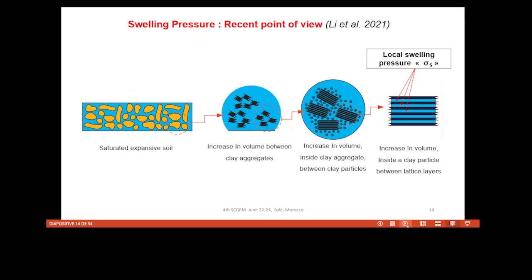A new point of view about the swelling pressure, because when we come back to the structure of saturated expansive soil, here we have the particles and water in case of full saturation. But if we go through the details of particles, we know that the particles are composed of clay aggregates, and we have some chemical liaison between them.